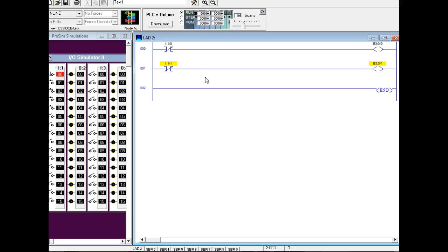What do you mean by an error? It wouldn't work. I mean, you don't get an error unless you screw something up, right? If you don't build that rung correctly. So this is not an error. The PLC has no idea what you're trying to do. It knows you can't put coils in series. It knows you can't put this there. It knows you can't do this. If the rung has the correct syntax, then you're not going to get an error. If you use the right symbol, your PLC is not going to give you an error, right?